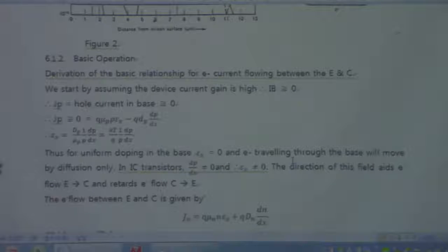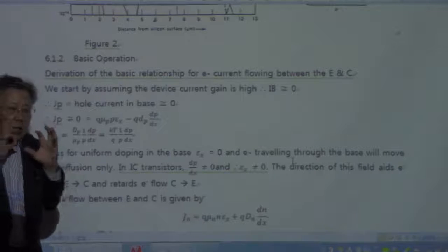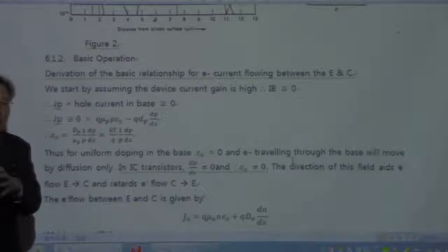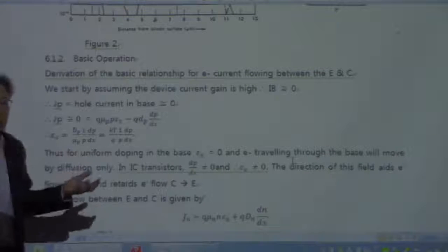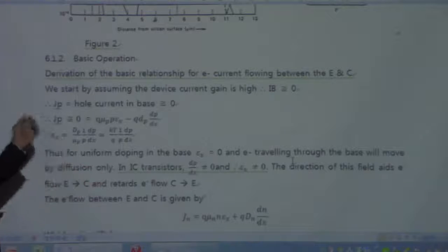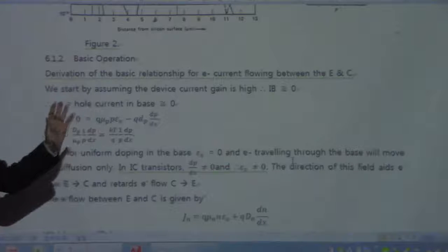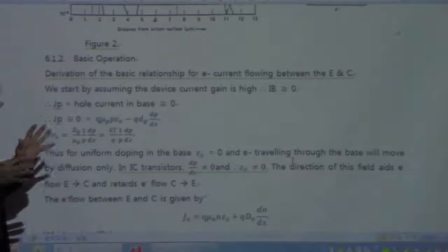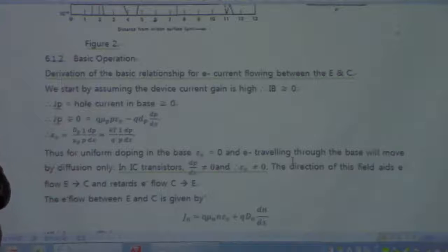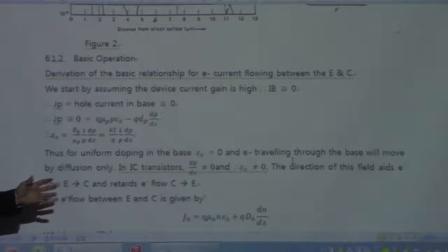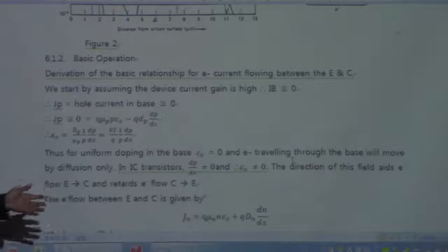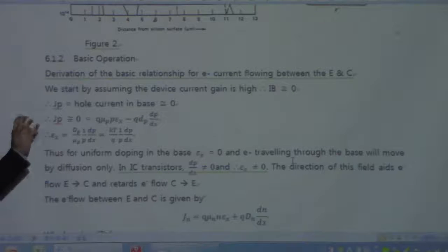On the other hand, in the MOS transistors, only electrons or holes are going to be involved in the drain current. So MOS transistors are called unipolar transistors, and then we can distinguish NMOS or PMOS depending on the free carriers. In the bipolars, we don't call that N bipolar, P bipolar, things like that, because electrons and holes are both involved in these transistors.